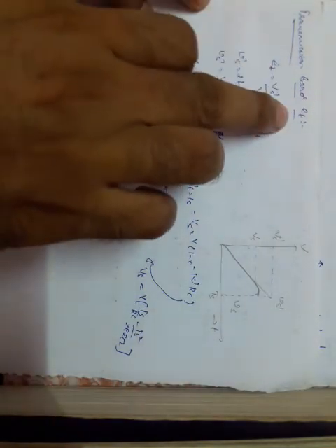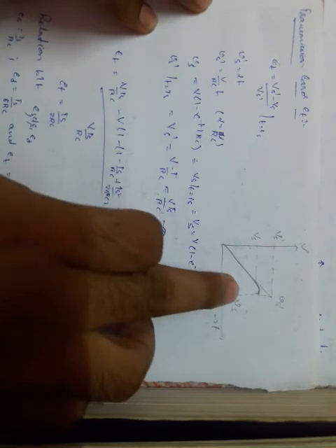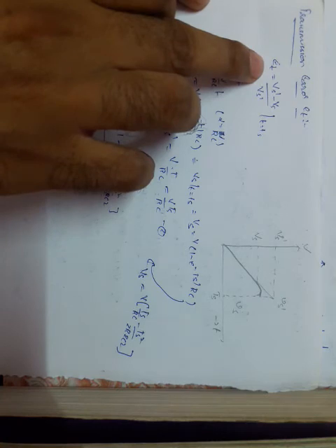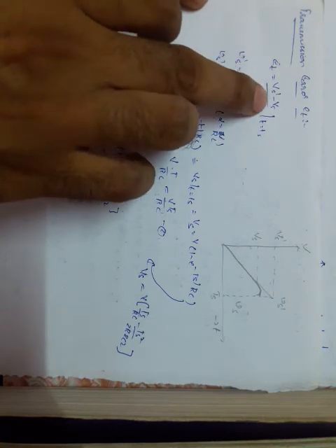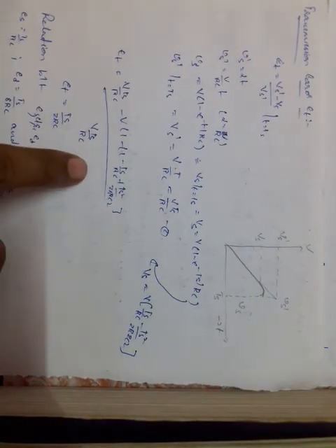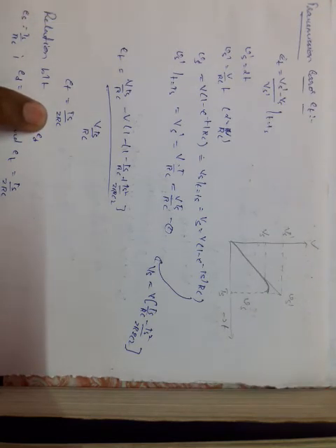The next error is the transmission error, that is Et. This is the waveform which we have generated here. Again we write down the formula. Transmission error is equal to Vs dash minus Vs by Vs dash, when t is equal to Ts. Again you substitute the value, and we get Et equal to Ts by 2 RC.